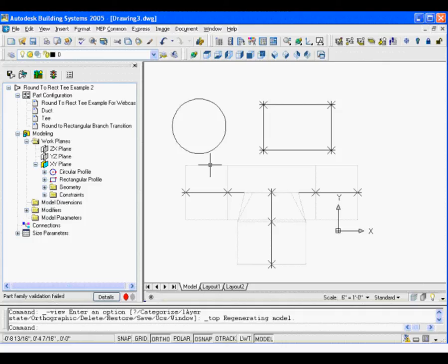Again, the most important thing to keep in mind is that you want to use Content Builder to build your part. You want to stay in this environment. If you had AutoCAD solids or something like that, go ahead and use the block-based part of creating parts. Create it as a block-based part, and take advantage of the 3D blocks or models you already have created in AutoCAD.